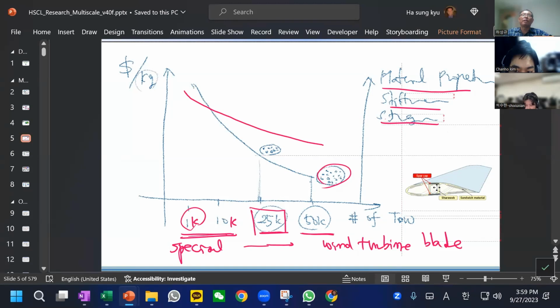50K heavy tow. And now the width of the spar cap is sometimes, I would say, 50 centimeter, and the thickness will vary along the blade. So it all depends on the design. Well, we can discuss a lot about the wind turbine blade, which is very interesting to a designer like us.